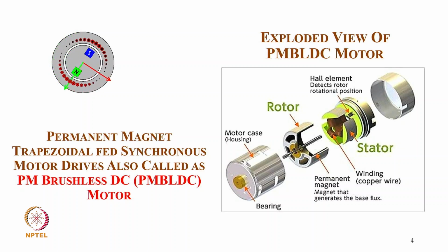position of the magnets, and we design the magnets and rotor in a manner that we get a trapezoidal back EMF in the stator winding, and then we excite the three-phase winding with quasi-square current, so that the torque is produced at any moment of time with two phases only. We excite only two-phase winding, and that remains constant for the different commutation periods, like 60 degrees. So it gives a constant torque similar to the DC motor with constant current, and we get the electronic commutation with the help of the inverter.